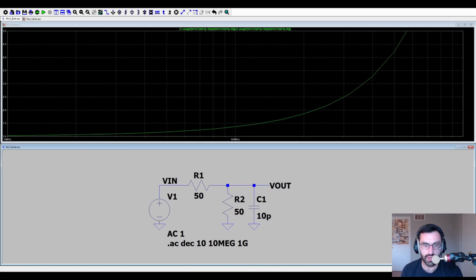And in this case, we are the load. To maximize efficiency, you want to make sure that you are as close as possible to a 50 ohm impedance for a 50 ohm system. And in this case, the 10 picofarad capacitor takes our 50 ohms and over frequency adds imaginary impedance to it, making it not 50 ohms, because unfortunately, imaginary impedances are quite real.